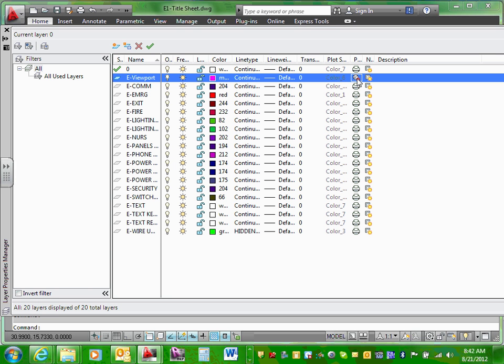You see that little X meaning the printer, anything you put there is not going to be printed. You'll see it, but it won't be printed. Okay, give me a thumbs up if you created a viewport and you put the color, any color you want, as well as you clicked on the printer, do not print. Cool? Jamie? Okay.